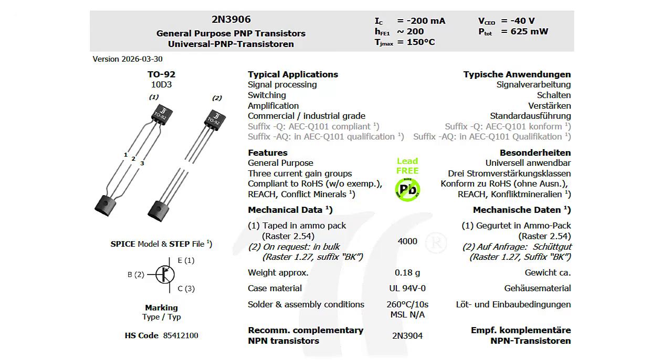When you connect the PNP transistor, you will need to know which of the 3 pins is the emitter, base, and collector. Looking at the flat surface of the transistor, the pins from left to right are emitter, base, and then collector. Remember that the arrow is always on the emitter in the schematic symbol.